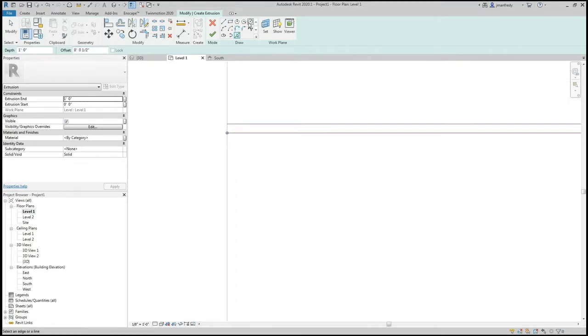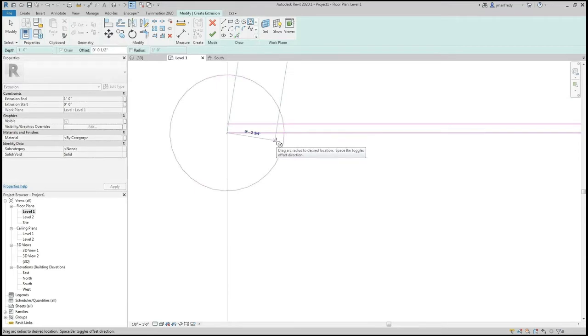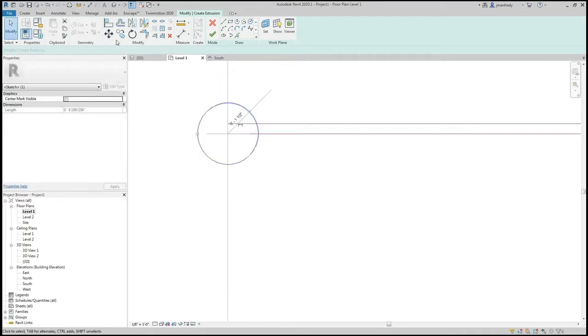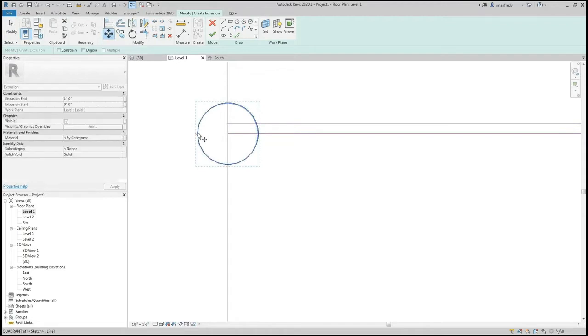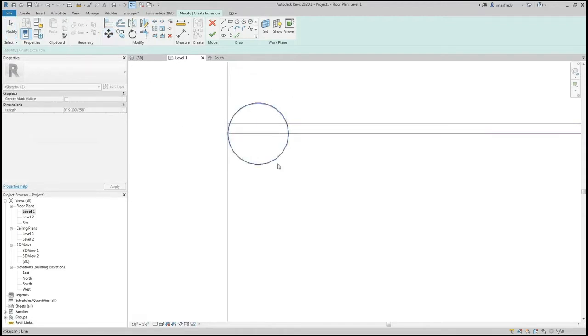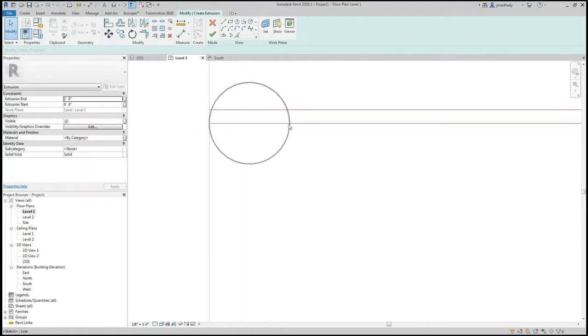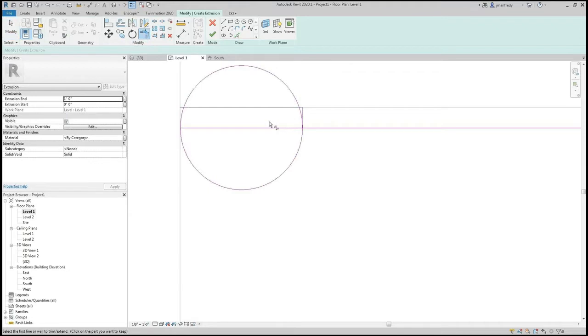And if I come into here, I can use a circle perhaps and draw a circle that has, let's assume, a 2-inch diameter, so a 1-inch radius. Now I'll take this circle and I'll simply move it over to there. And then I will trim this, so I have one object here that I can copy or array across the entire wall to produce that design. So I'm just going to draw some little guidelines here. I will trim these edges with the TR command.